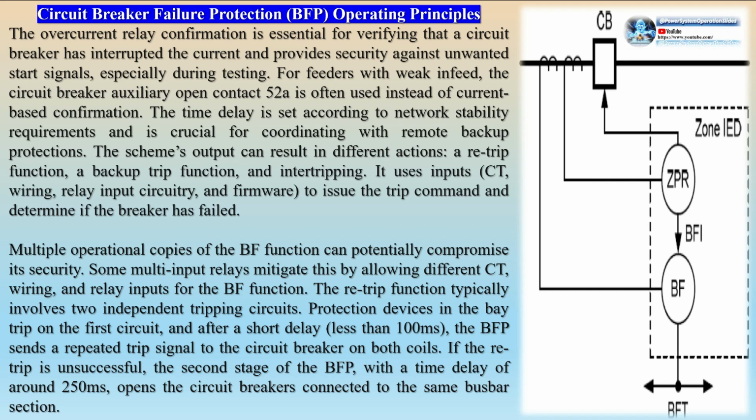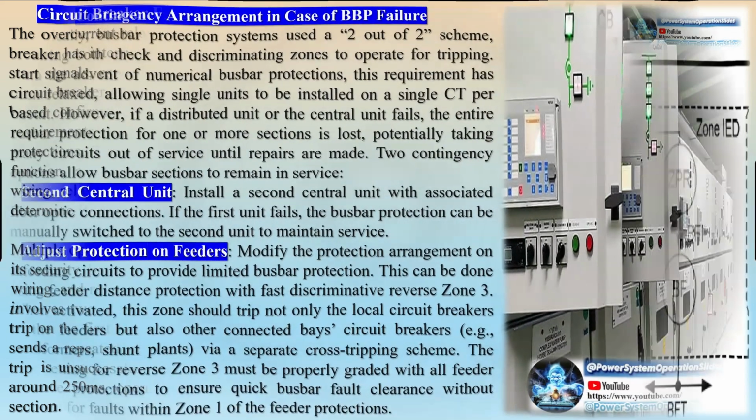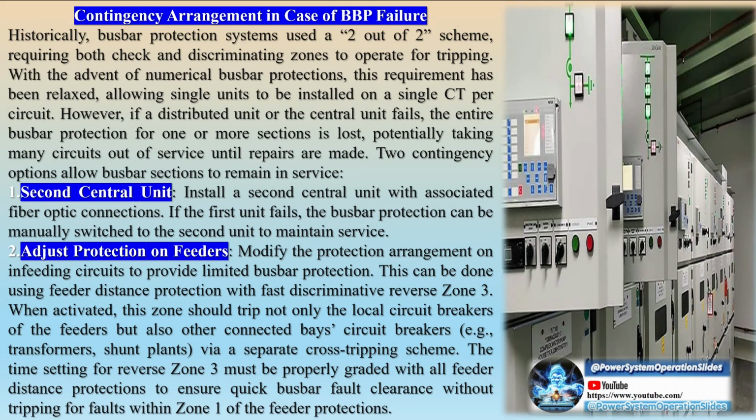During the maintenance of busbar differential protection, it may be necessary to adjust distance protection settings: X reaches, R reaches, or grading times. These adjustments are sometimes required to ensure the stability of the generator in the area or to maintain the integrity of the GIS busbar in case of a fault during busbar differential protection maintenance. Additional tripping criteria for BBP differential: check zone to prevent maloperation due to disconnector auxiliary contact failures.